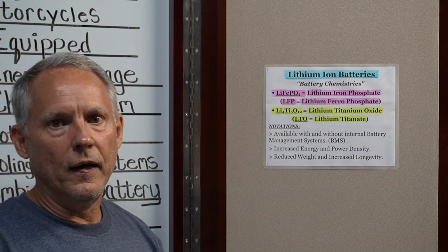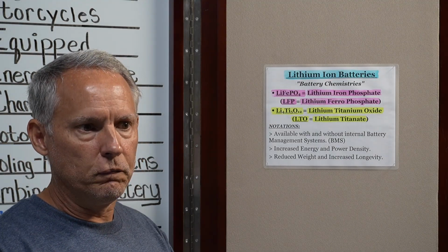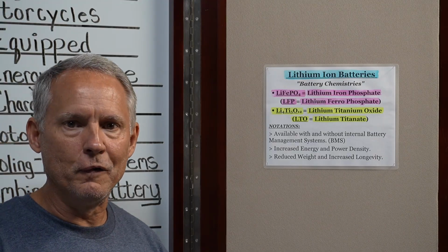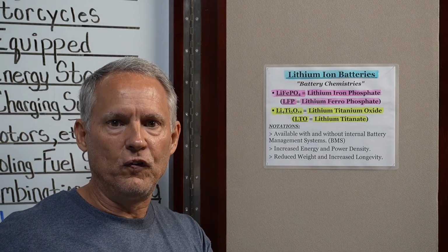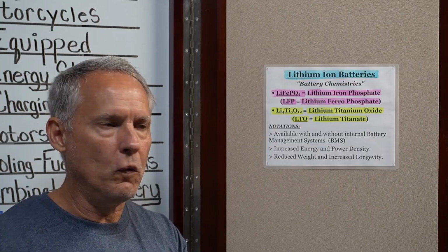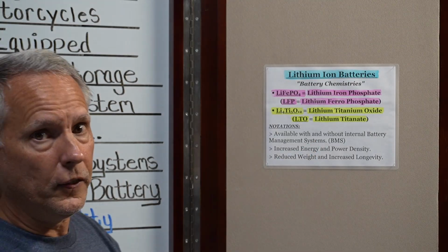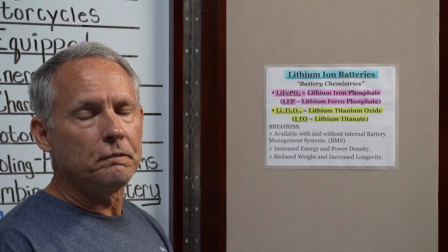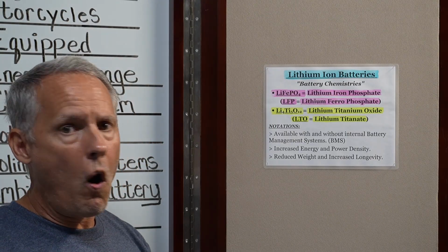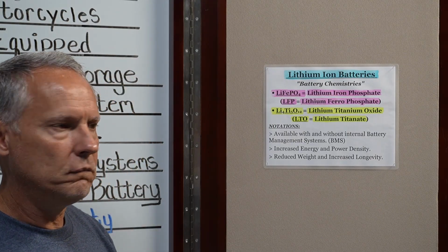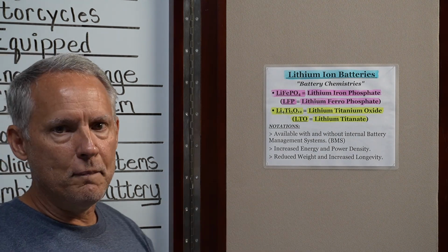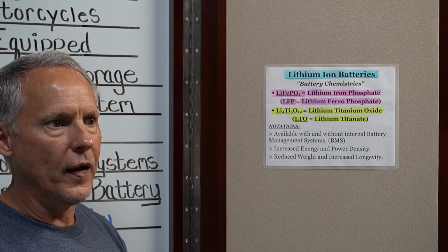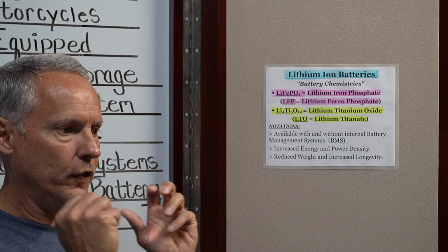If you're going to put it in a daily vehicle of any sort, a regular passenger vehicle or, like I said, motorcycle, boat, somewhere where the battery is out of sight, out of mind, and you're not monitoring it in any way, an internal battery management system is your friend, okay? So what are the benefits of lithium-ion batteries? Like I said, I'm going to have a video all about this, but just roughly, increased energy and power density. For their size, they have a lot of energy, and can deliver a lot of energy at a great discharge rate.